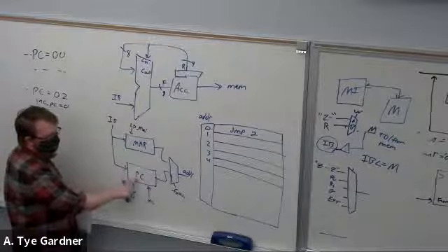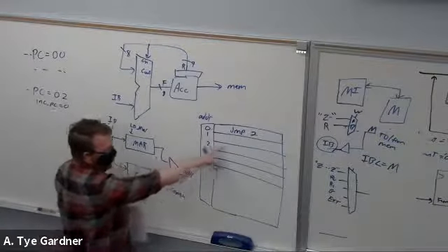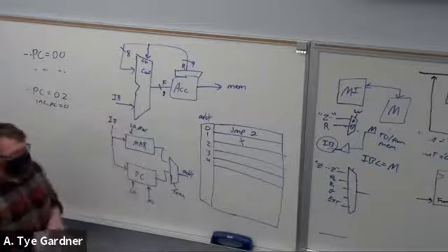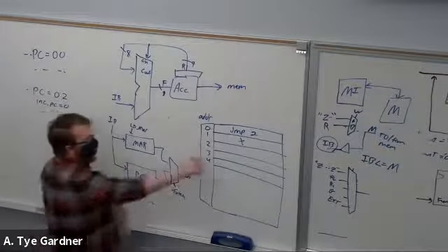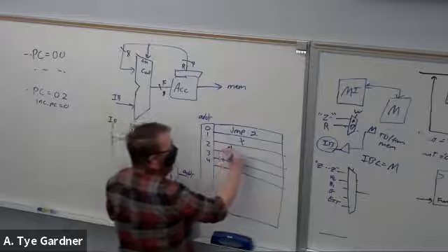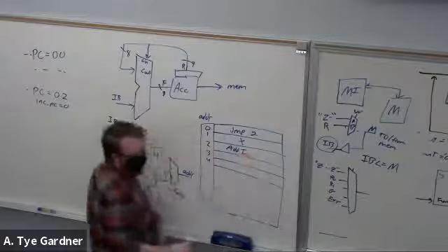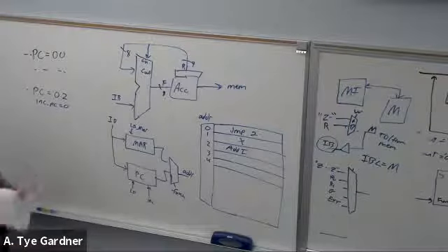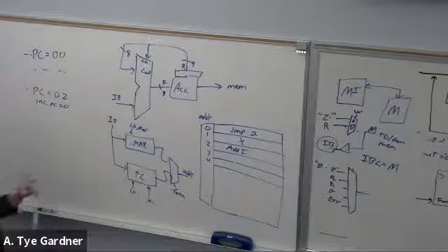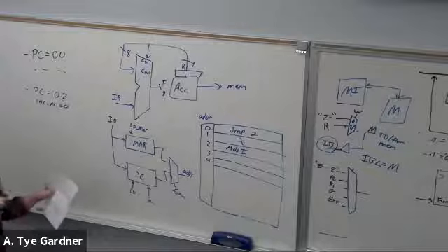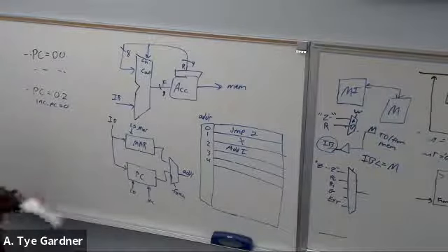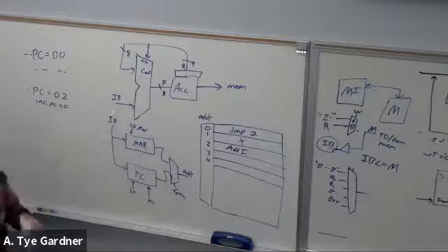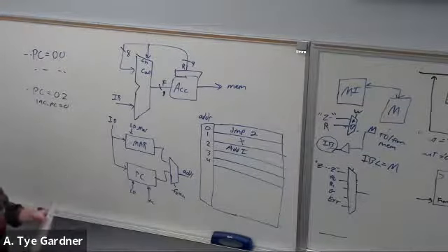And then we can start counting. Now our PC says 2, we select fetch, we have 2, we jump down to here. We've ignored whatever this is, right? And now I'm sitting here and now I can do like add immediate. Well, add immediate says right after this clock cycle, the memory is going to provide a value for you to add to whatever is currently in the accumulator. Well, I just started, so the accumulator is 0, so I could also send the load command.